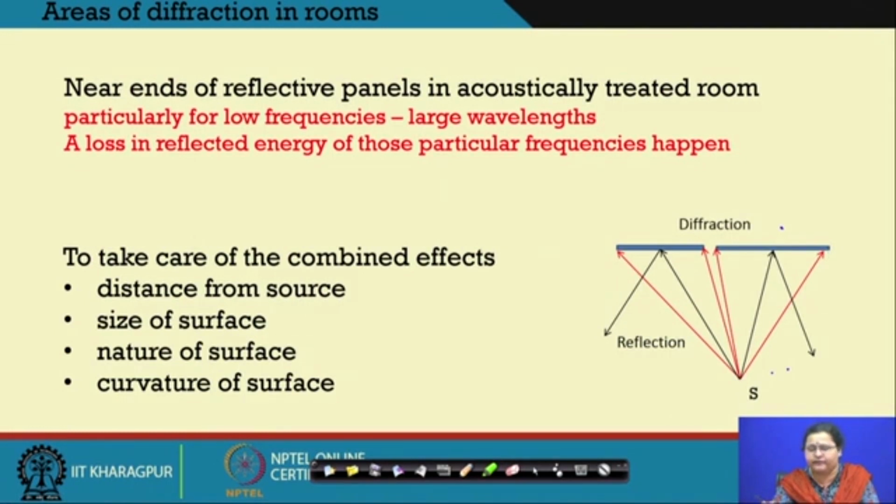So, you have to be careful about the length of the reflecting surface, so that it does not allow diffraction. If you require diffraction, then what is the dimension or gap that will allow it? You have to go by the dimensions shown in the first slide, which are within our audible range, and choose the size of the reflectors either to allow diffraction or not.